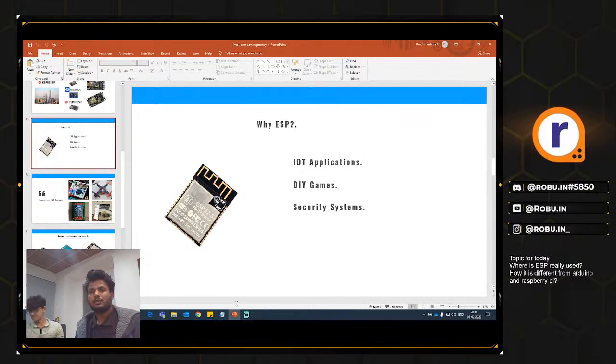Okay, so I actually did a project like this. There are options in code where you can shut off a specific Wi-Fi if you require. You can name them in two different ways, like Wi-Fi 1 and Wi-Fi 2, and you can specifically close one of them, then give some delay for a few seconds, and then connect it again, because hardware needs some time to shut off and shut on, so you need a little delay for that.